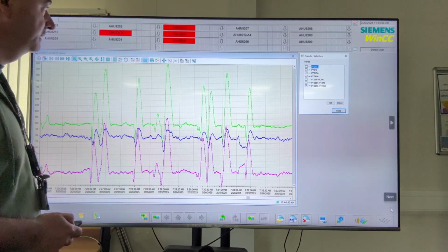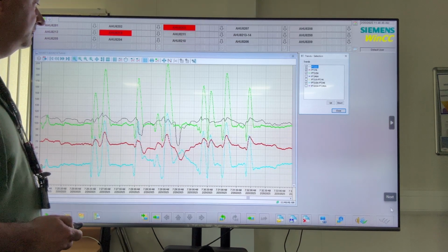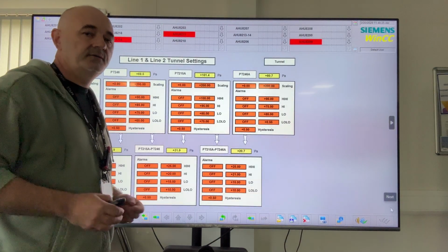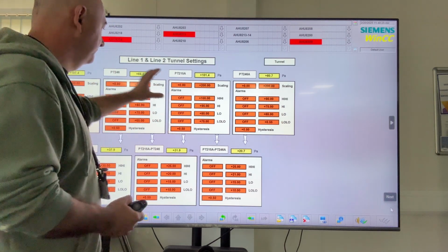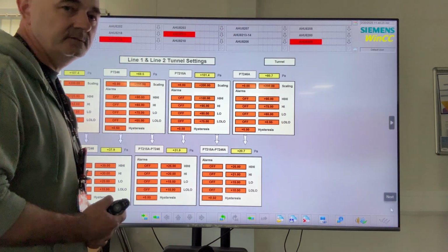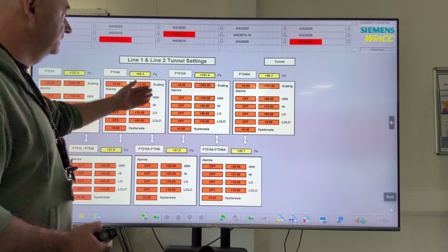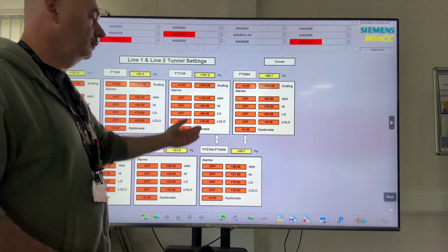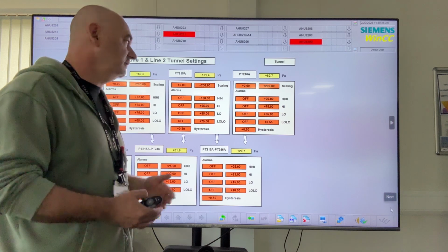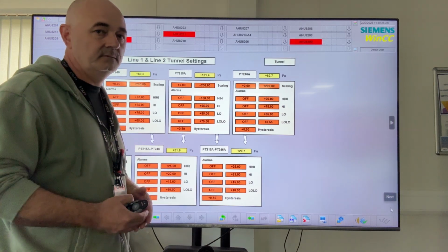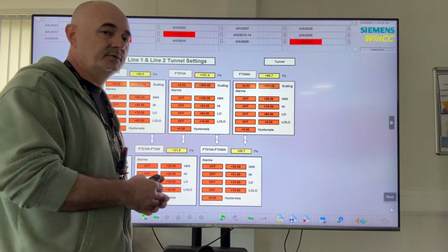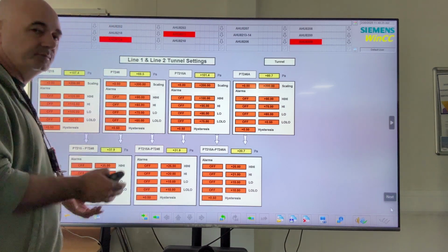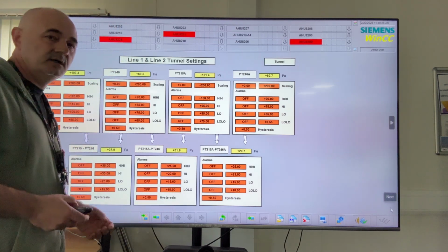cause. And to make sure that I'll be aware if a room goes wrong, I designed this alarm page. With the limits, I have high and high-high limits, or low and low-low limits. The high limit is a warning; the high-high is already an alarm. So I want to know before production if something goes wrong, to save the production and to keep the machine running.